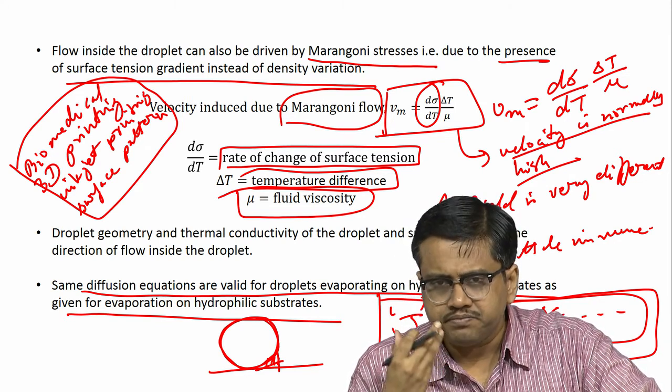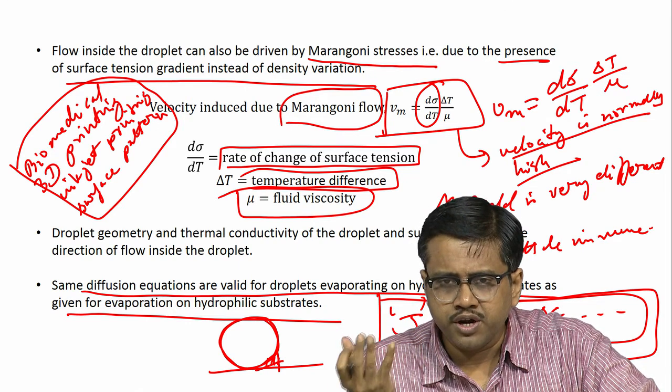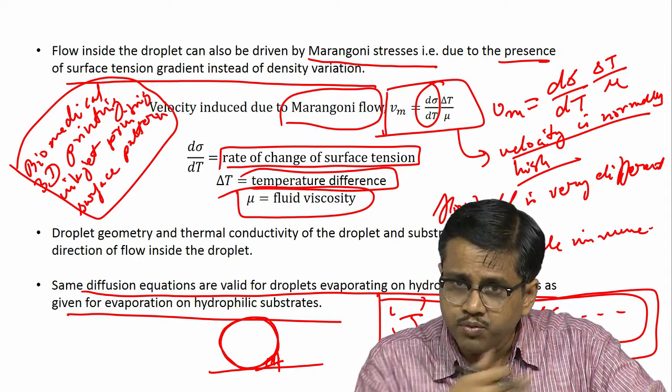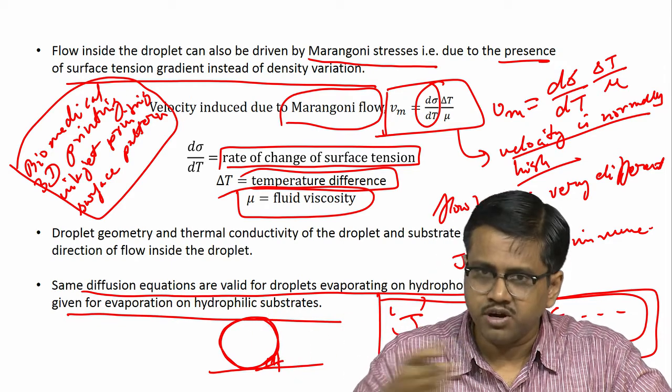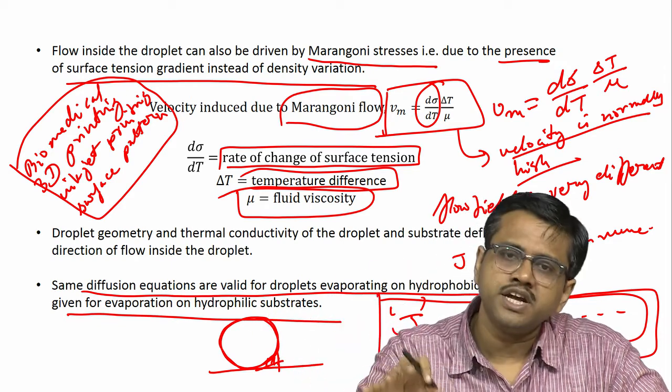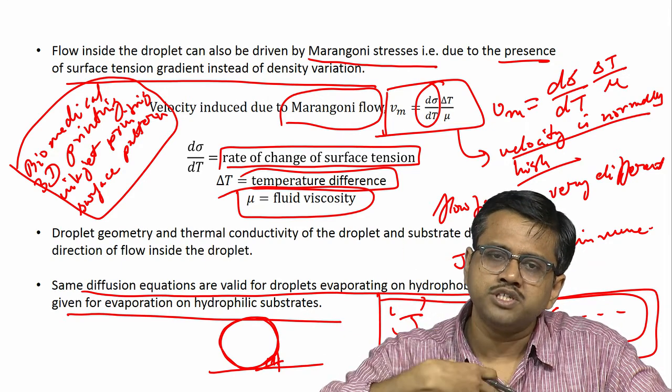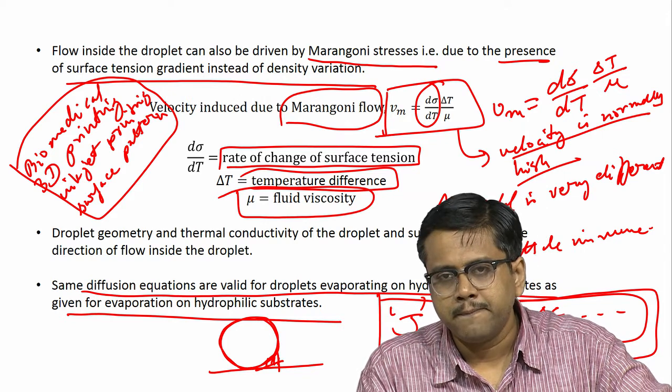That means normally if you allow it to evaporate normally, it is a diffusion driven problem. As soon as you blow, basically you are removing that saturated region of CS and you are replenishing it with a fresh stock of air, right. So, naturally the evaporation becomes a lot faster, right.